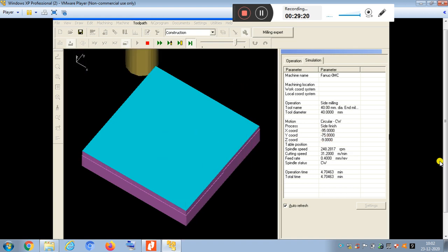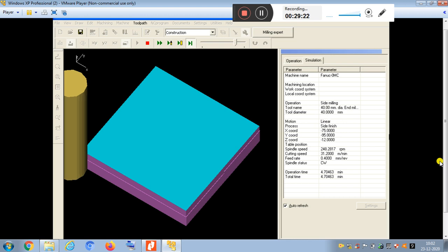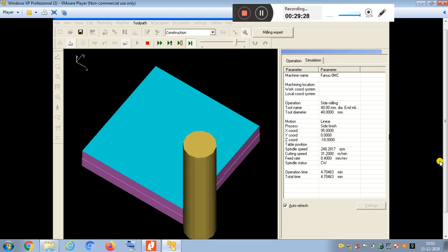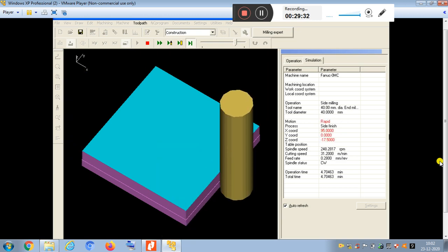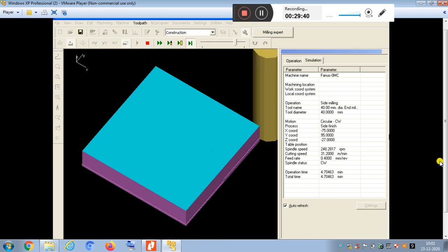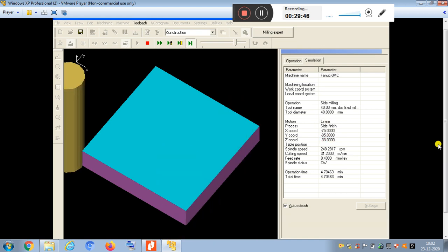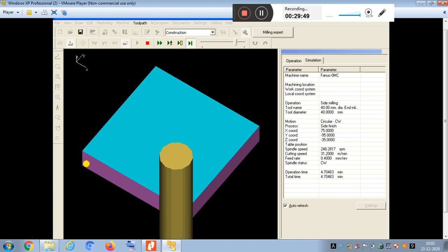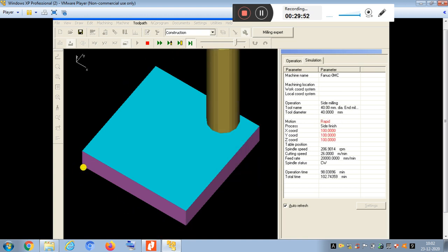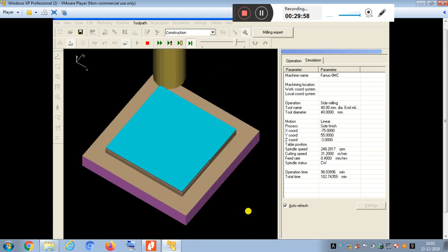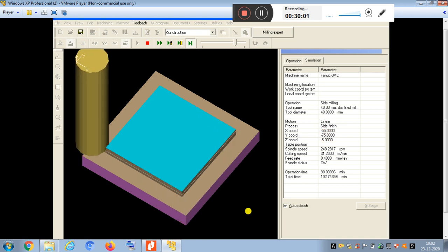In the roughing operation, it is removed in only a few steps. See here, this is the finishing operation in the side mill. It is removing minute particles, a minimum amount. Why I have taken this is, if you take exactly 30, the remaining part may attach here. Because of that, if it is more than that, no part will remain here. Okay, this is the second square, a side mill.